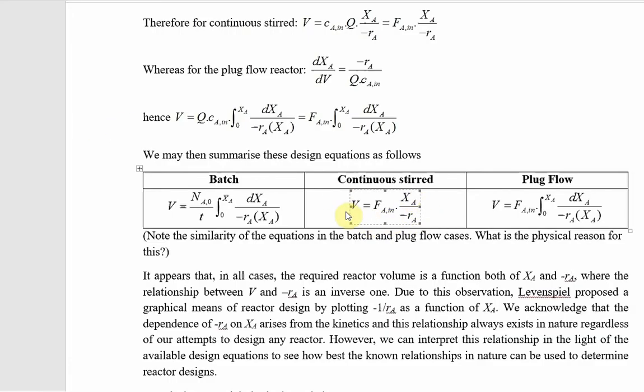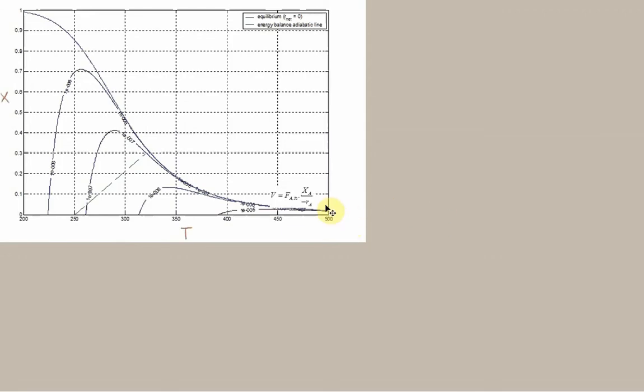So we've derived and we've shown that that is the design equation. So let's just put that in here, and let's consider how we can calculate this volume. So if we just expand this out, noting that our reaction rate is the difference between the forward rate minus the reverse. That's k1 C_A minus k2 C_B, which is equal to k1 C_A0 (1 minus X) minus k2